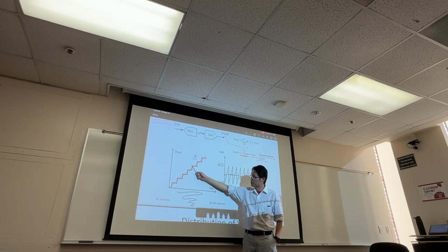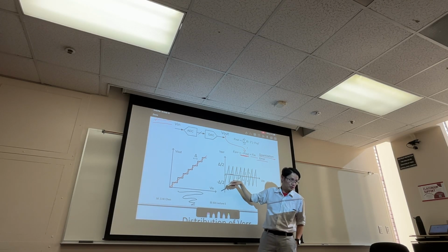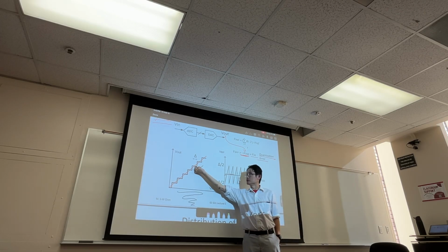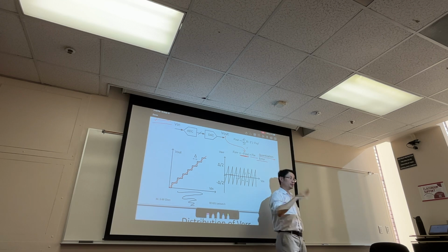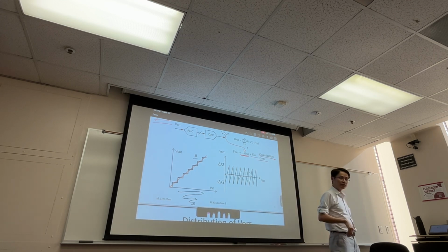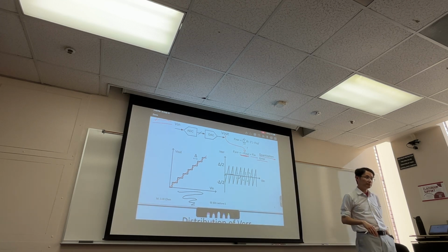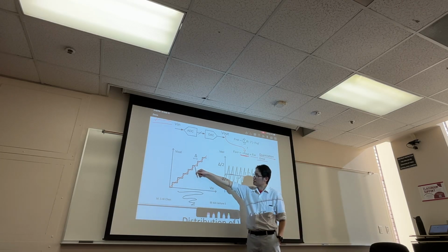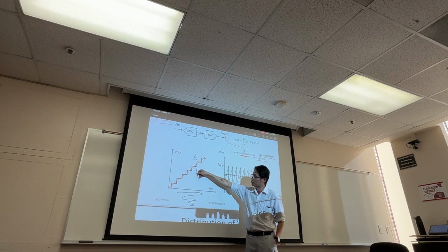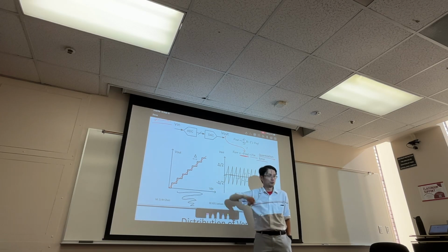If you are uniformly distributed within 1 delta, you probably can still sample all of this, it's okay. But just imagine if the input is just a fraction of this delta, you are not uniformly distributed between delta over 2 and minus delta over 2. You guys see that? You don't, because you're going to be centered around where your input range would be.